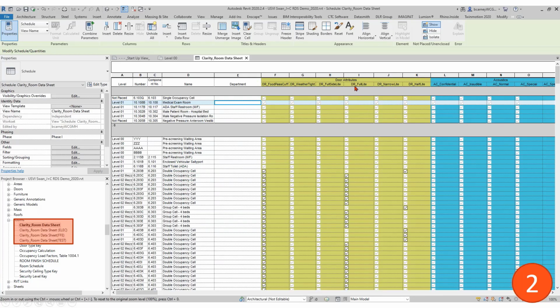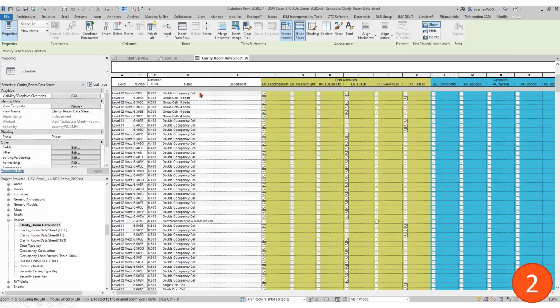It takes forever. The other thing to know about is some of these extra columns that are newer-ish with Revit, but a lot of people don't use them. If you use those features, like striping, it helps. You can freeze your headers, so as you scroll up and down, this information stays at the top. And then use the shading to shade the columns, just like in that Excel file, so you can graphically know what you want to look at. All of that does help quite a bit.